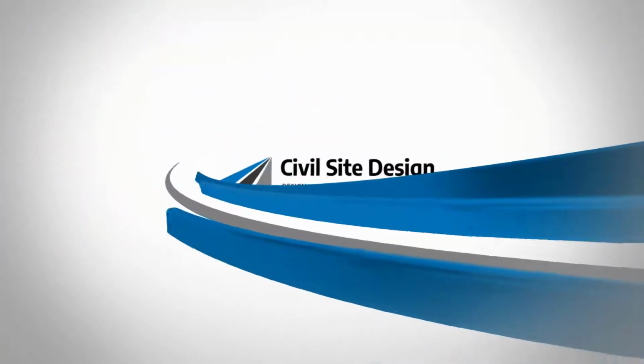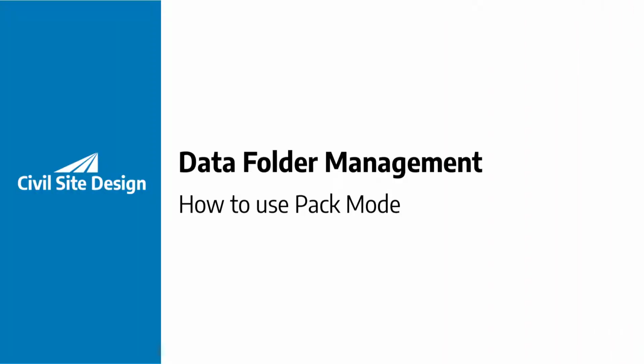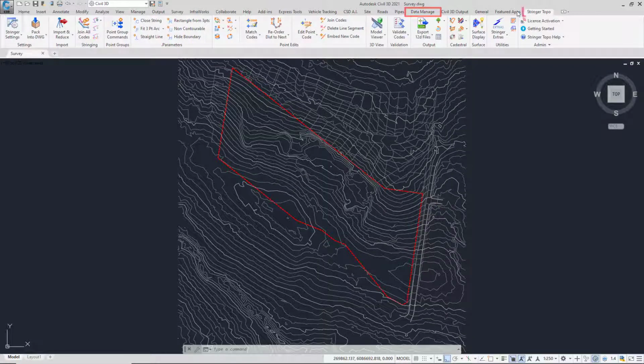Civil Site Design and Stringer users have the option of using pack mode, which will place a zipped copy of the data folder into the drawing, essentially making the drawing more portable. Here's how it works. Firstly, the pack mode toolset can be found for Civil Site Design users on the Data Manage ribbon. For Stringer Topo users, this can actually be found on the Stringer Topo ribbon under the Settings panel.